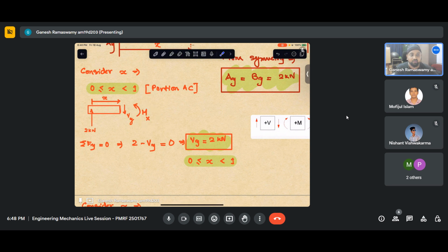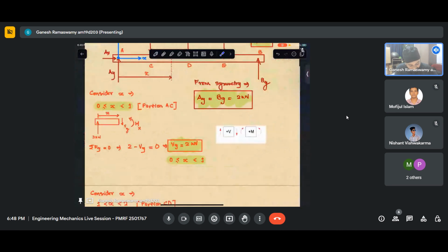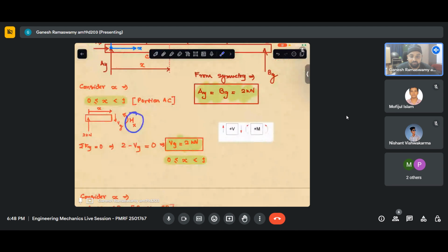And if I go about plotting it in a similar way as I did for the shear force diagram, I will have the bending moment diagram. That is all there is. But at times, our bending moment will have some dependence on x, maybe linear, quadratic, or cubic, or whatever. In such cases, it is important for us to know because you can draw a parabola in two ways. So we should be able to gauge which one is the correct way to go about. So we should essentially relate our moments, our shear forces to the applied force and go about solving the problems.